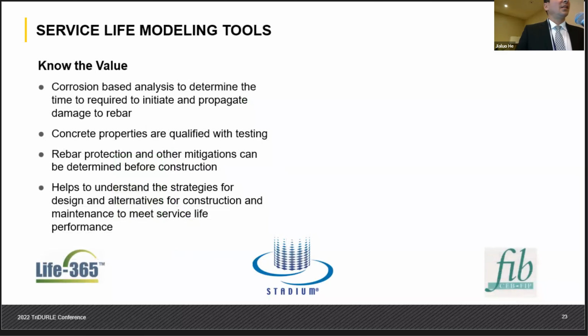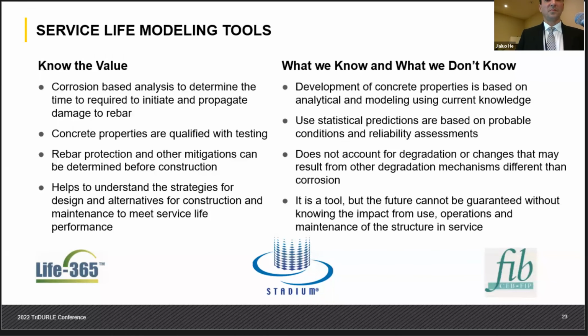And then understanding the tools. This is a tool. It's not going to give you the entire spectrum of everything you can think about. It's just a tool. So what the tool is telling you, right? The corrosion-based analysis to determine time required to initiate and propagate damage, right? Qualification of the concrete with testing, rebar protection and mitigation, right? You can make determination of that. You can make a determination of the strategies of maintenance too. And that's what we know, what we don't know.